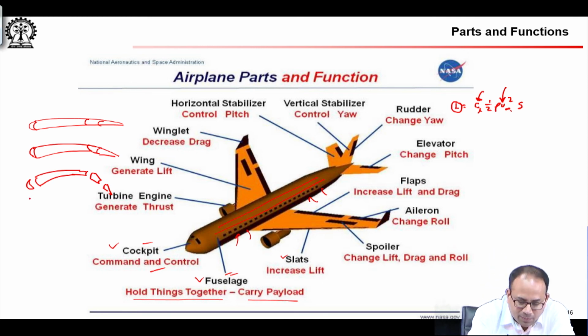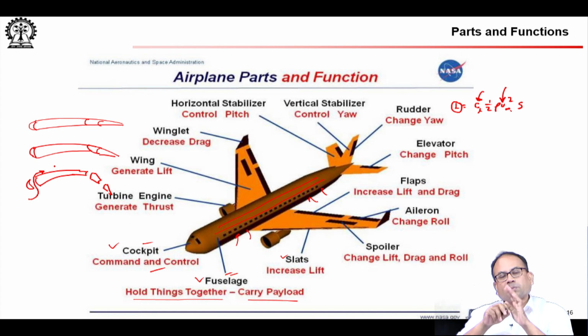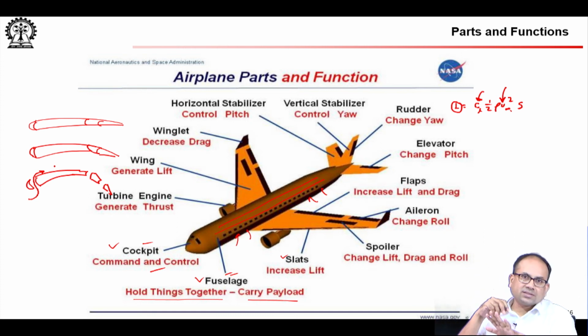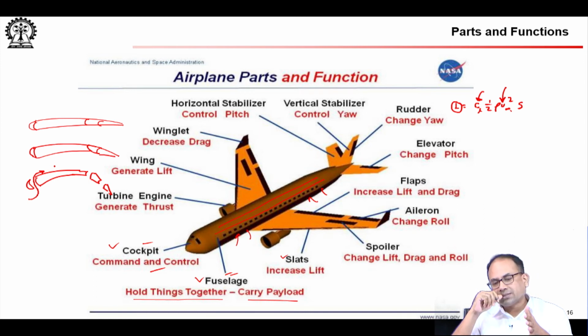And remember the purpose of the leading edge slat was to introduce some high velocity air into this region, so that the flow does not separate. Now, we have not talked about what flow separation is, but the next lecture will be on the drag of airfoils, and we will look at it, but at this point just keep in mind that your slats can open up.